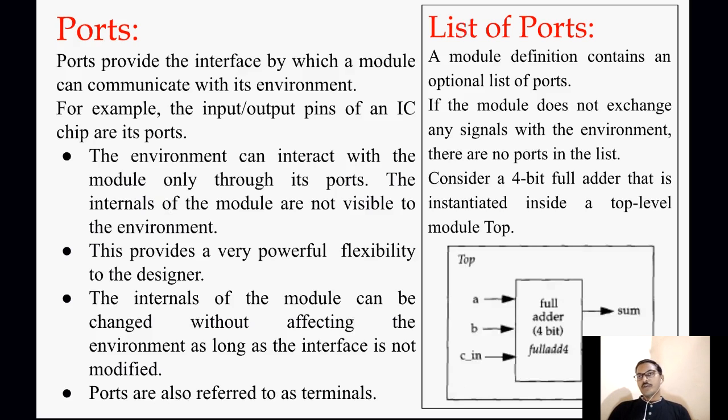Here you can see at the bottom we have defined this particular module, that is top, containing the full adder, that is 4 bit. The module name is given as full_add4. What are the ports? A, B, and C_in are inputs, and the outputs are sum and C_out. That is nothing but a port list.